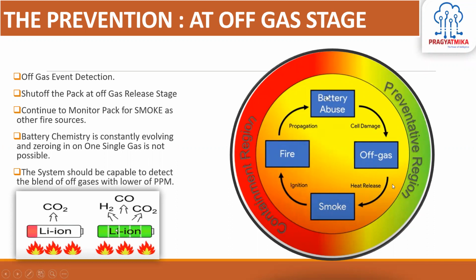Either you do the load cutoff, or you might have a valve in your battery pack which you can open so that if there is an excess of gases being produced in our pack, those gases get released. If the gases are being released, there is no way that the cell capping or the battery pack casing will explode.